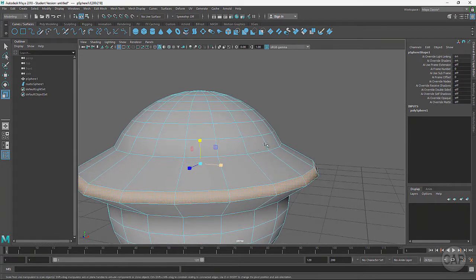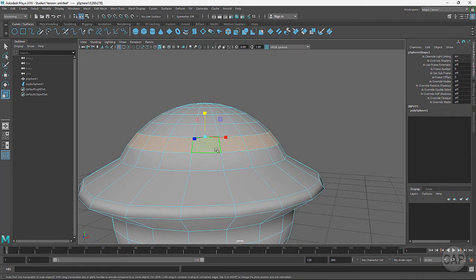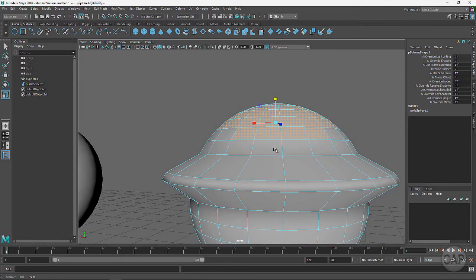Okay, so with selecting, right now we're just selecting one by one. We can hold the shift key down and select multiples. I can double click, send a loop all the way around of selections. And then I can also use the marquee, which is dragging that marquee across the scene with the object, and it will select both sides. So it's selecting 3-dimensionally, so it's selecting the back side as well.